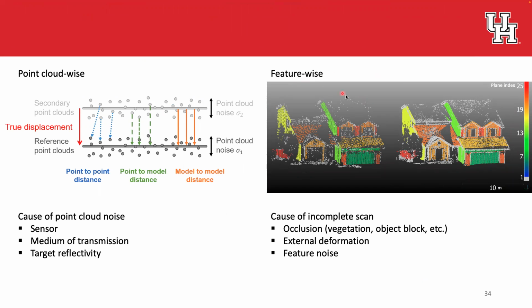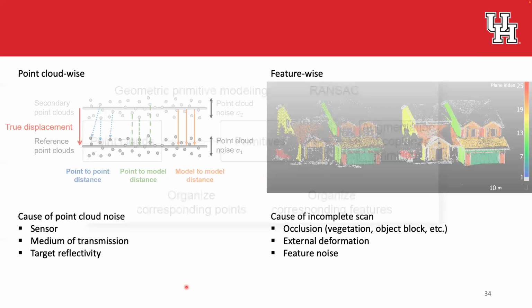We have mobile laser scanning. On the left here is the 2015 data. On the right is the 2017. And you notice the point clouds don't quite look the same. We have some occlusions due to differences in vegetation or parked cars or different viewing angles, etc. But what we want to be able to do here is automatically extract planes from the figure on the left, automatically extract planes from the figure on the right, match those planes together, and then use that matching to estimate how much the fault line has moved in the intervening 2 years.